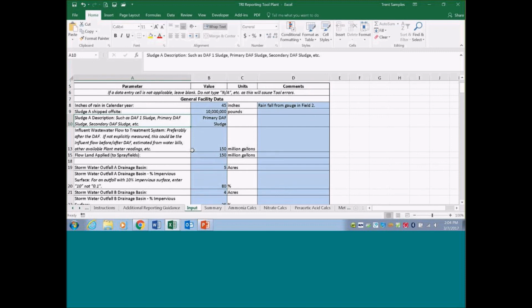because questions will arise if a regulator comes out and does an inspection. They'll ask for you to provide proof why you didn't report a certain chemical. Yeah, we've noticed, just off topic for a moment, that EPA seems to be trying to internally do some data integrity checks. Maybe they're noticing that you're subject to RMP because of your ammonia refrigeration system, but they've never seen you report ammonia on a TRI. It's good to have that backup calculation to say, here's why I'm not reporting ammonia for TRI, because we're noticing that EPA is starting to ask that.